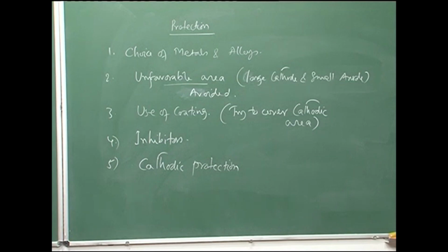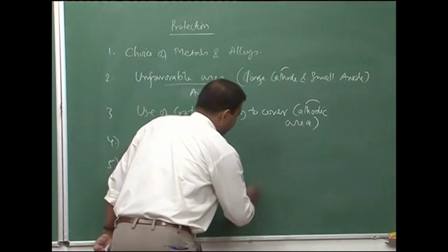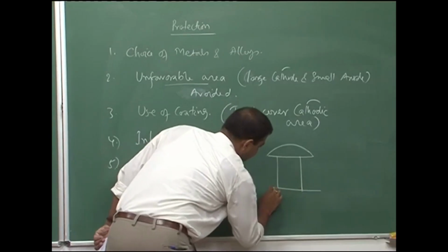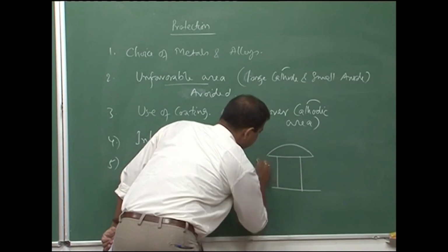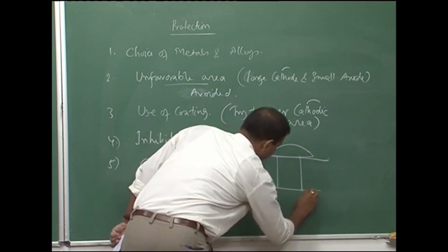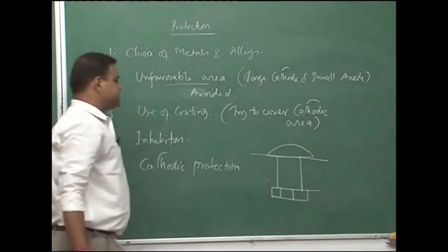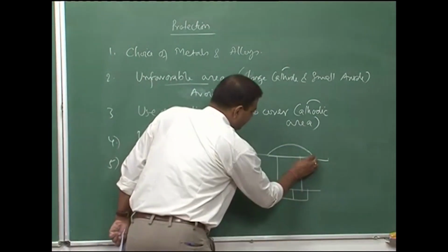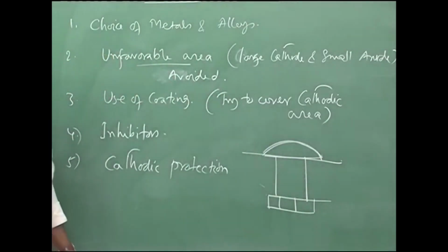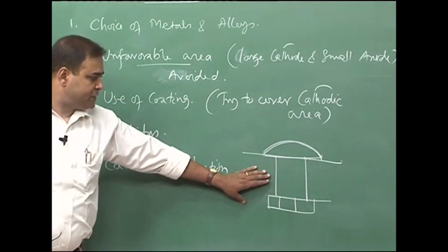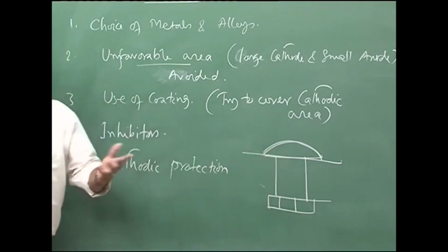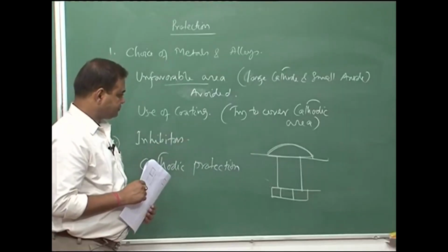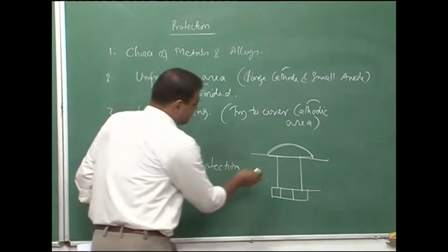Now, another position where we can experience galvanic corrosion, let us say we have a threaded joint, these plates, this is basically the threaded joint, and this is, let us say, a screw or threaded bolt. In most cases the bolt material would have higher strength compared to the material which is being fastened, and the bolt would be a different material compared to the material which is threaded.